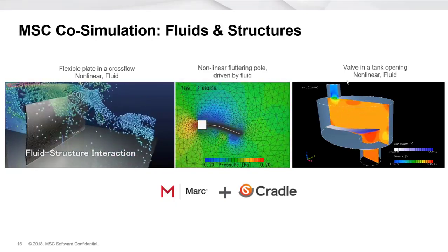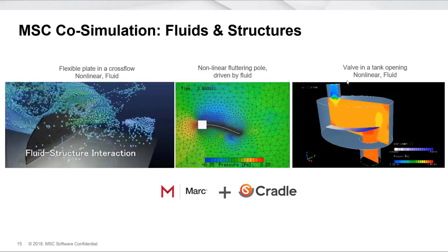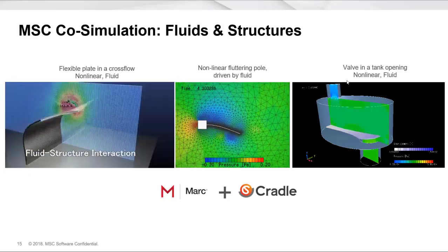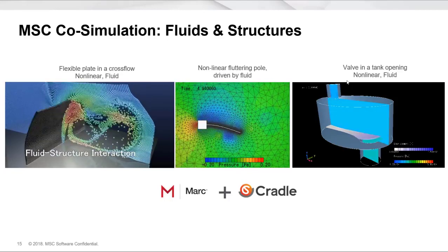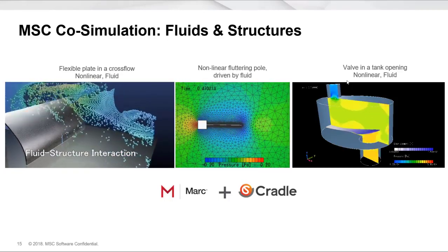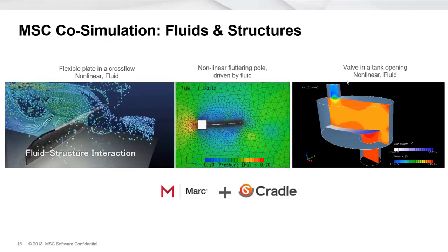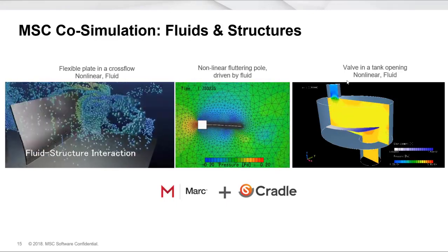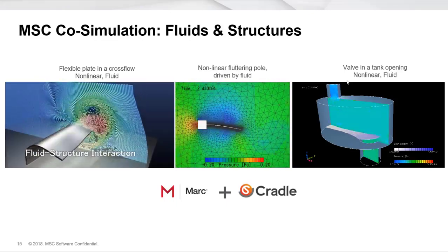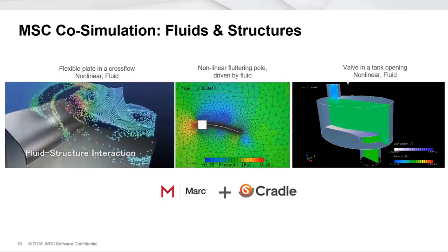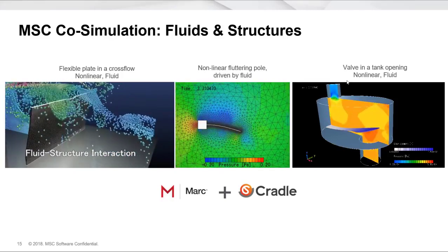Now on the right, you can see a really nice example of how that can be used practically. A reed valve. The fluid pushes up the reed valve, allowing more fluid to flow through the chamber, and of course as the pressure changes, the amount of fluid into the chamber changes. What's more, as the reed bends, its stiffness changes, which pushes the valve closed. So ultimately, that's going to reach an equilibrium.